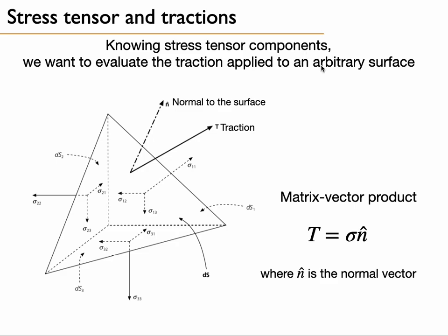into the material. So now you can think about your 3-dimensional axis, and now we take a cut, an oblique cut through the 3-dimensional material, and there will be a normal to the face. The face is defined by the normal, and if there is a traction vector, it can be computed using the stress tensor and the normal. So to compute the traction, we set it equal to the product of stress times the normal of a face.